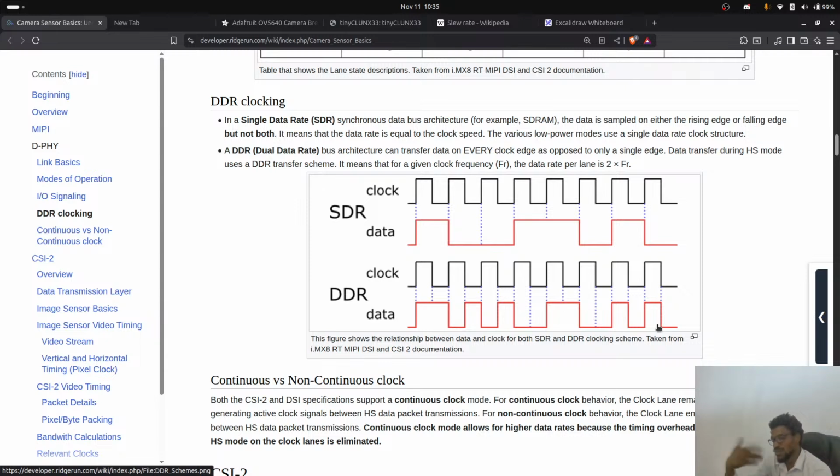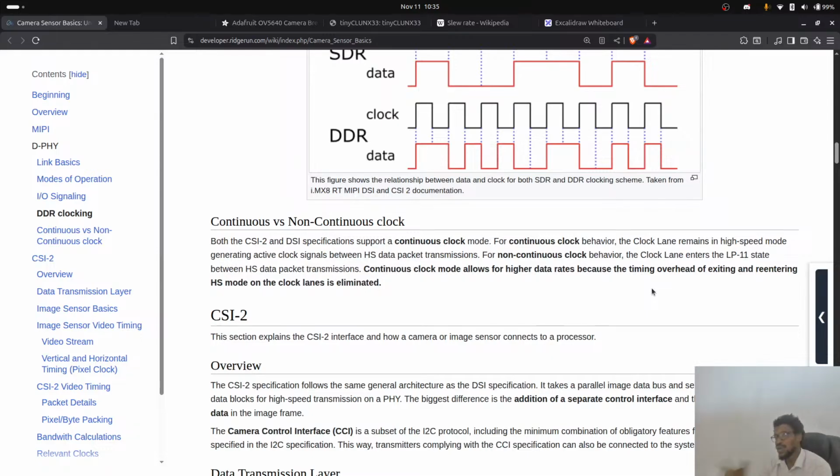So they're getting really a lot of samples, and really the speed depends on how fast you can consume them, not how fast they can get signals from outside. So what am I saying? With DDR, you get double the speed compared to SDR, and this is one of the things that makes MIPI fast. Because MIPI is capable of doing DDR, or rather in high-speed mode, MIPI does do DDR, and because of that, it can transfer images much, much quicker than, say, single data rates.